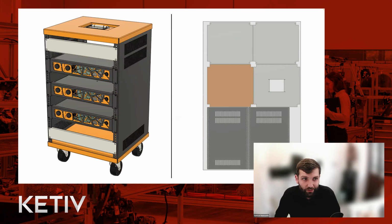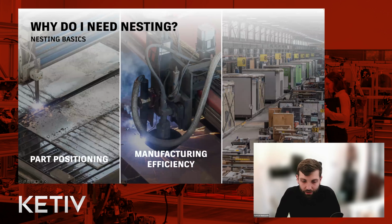And excited to dive in for sure. So why do we need nesting? Well, I've already mentioned it's about part positioning. It's about taking those folded pieces of geometry, if you think about sheet metal, flattening them out, and then laying them out in such a way to be as efficient as possible while minimizing the overall cost. If you can lay those parts out in the most efficient way possible, you're going to use fewer sheets, and overall you're going to save money and minimize costs.